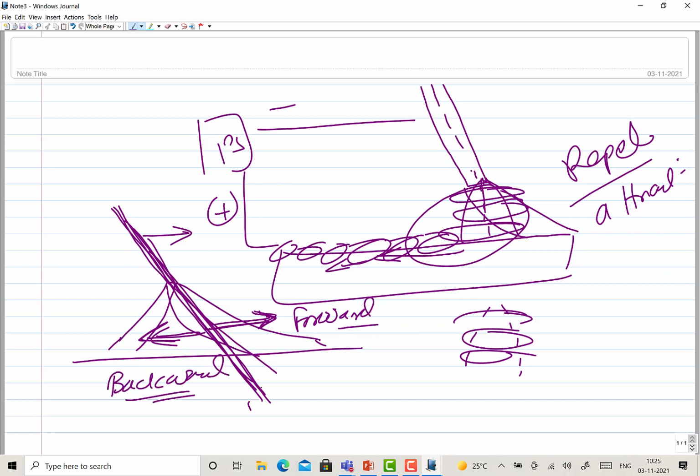This simply depends on the direction in which the welding is being done, or the heat source is being moved. Let's say this is the arc. Due to the deflection, the arc moves from this to this location. This is the already welded section, and this is the section yet to be welded. So this is an example of forward arc blow. If the arc is deflecting backward, then the arc will be directed towards the already welded section, which is backward arc blow.